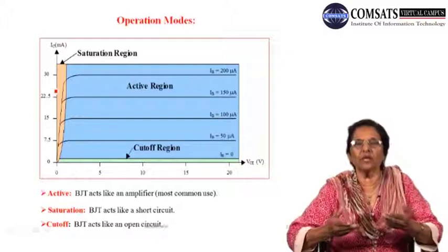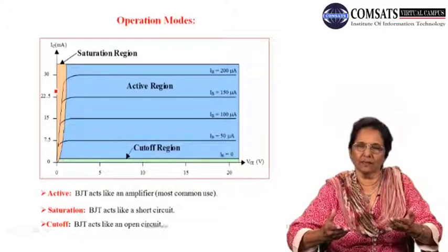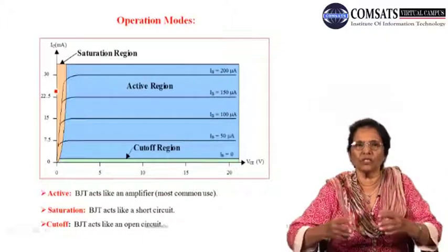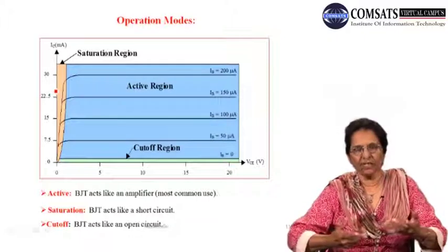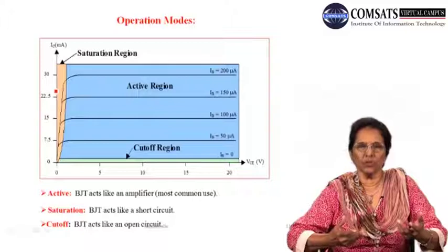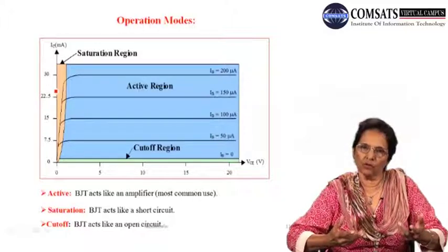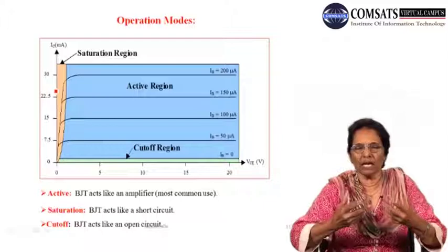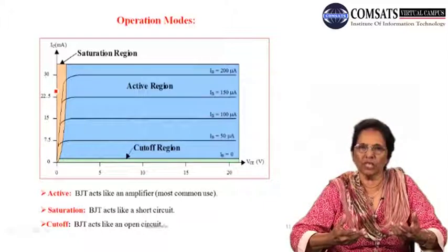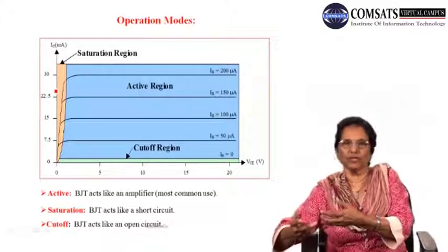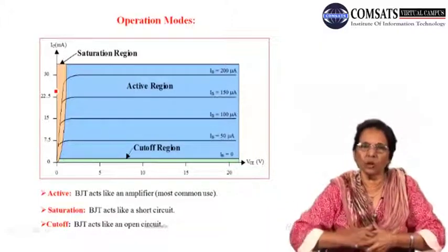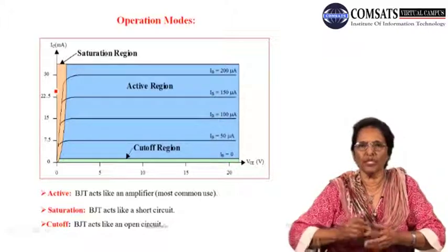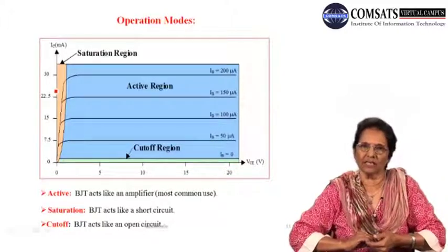So you see that your bipolar junction transistor in the active mode of operation is already acting as a DC amplifier. That is, if you bias the emitter base junction in the forward mode, then it will allow current to flow through the emitter base diode, and that current from the emitter passing through the base is ultimately transported all the way to the collector terminal, where it is collected and designated as the collector current.